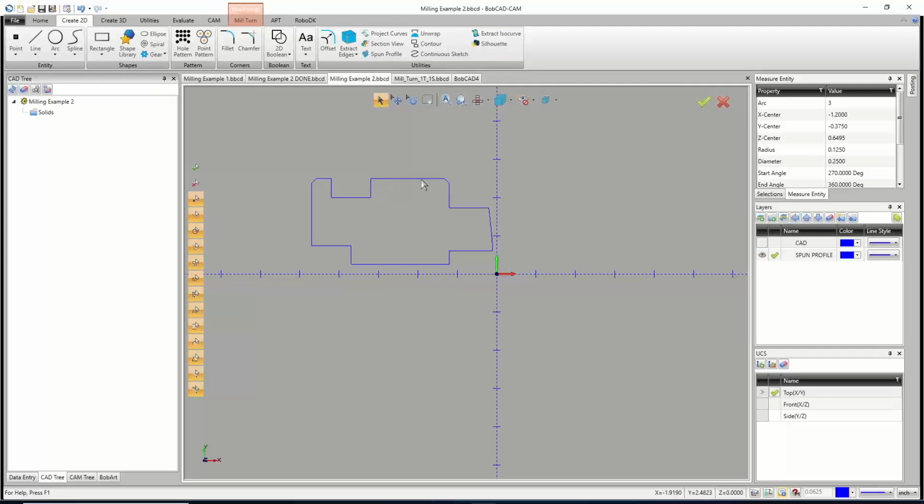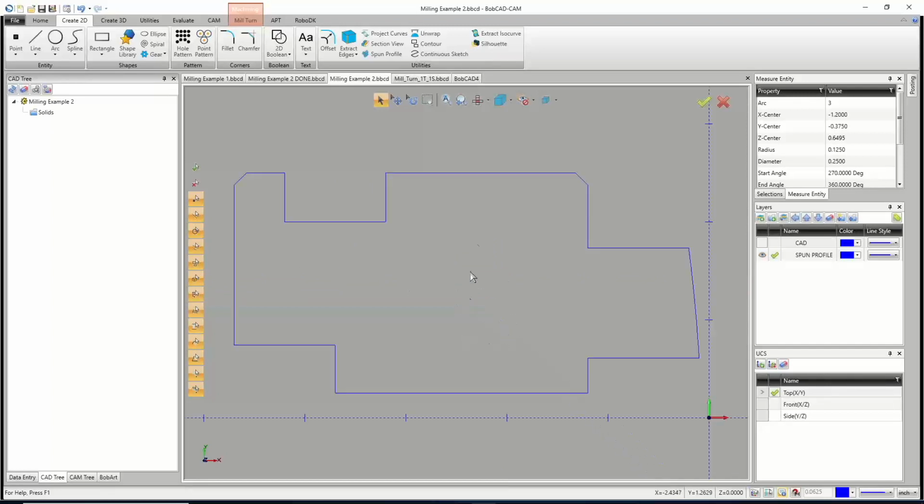When you hold shift and click, the whole thing lights up and you think, all right, great, everything's good to go. I'm ready to run with this thing. But what ends up being the case is because I held shift and clicked this way and the chain went around the part, it naturally stops at this line. Well, guess what? If there's a problem with that line, with that corner right there, then you'd never know it.